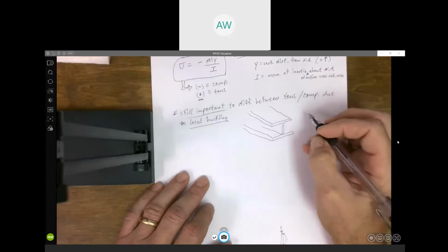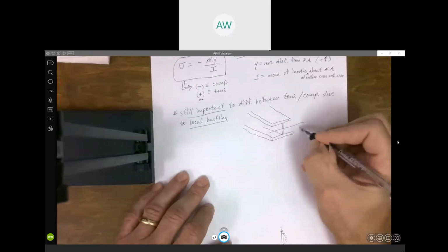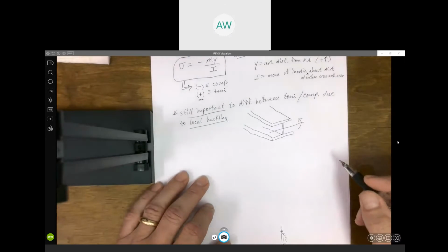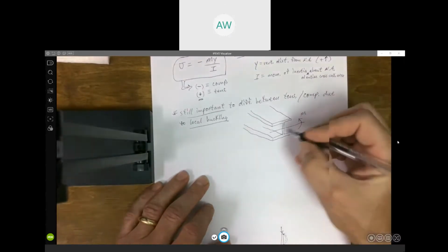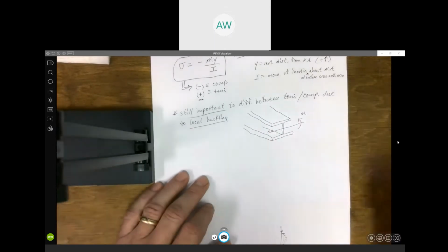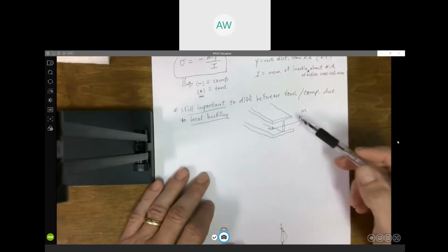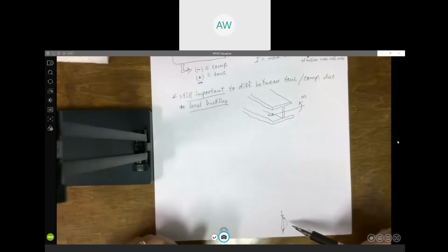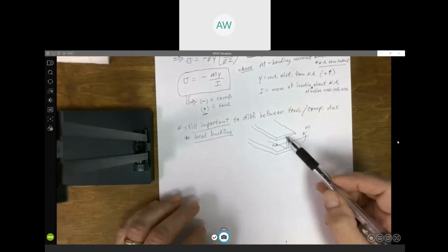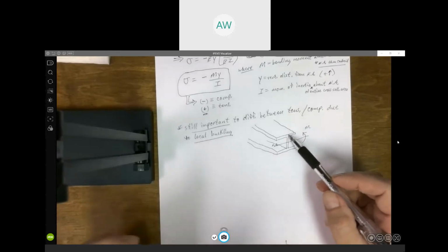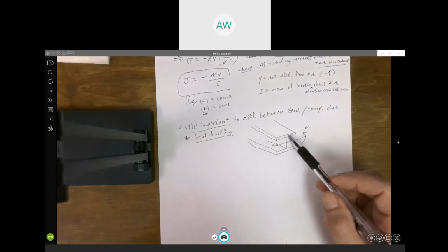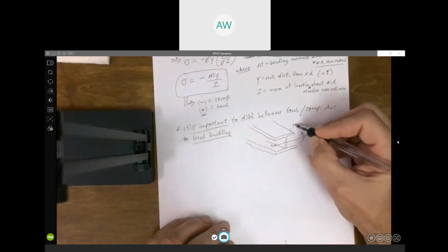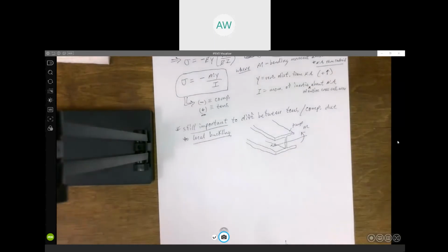All right, well, if we bend this thing, say we bend it this way, we apply some moment here. Everywhere above our neutral axis is going to be in compression. Well, that's not going to buckle like this axially loaded member. But if you have really wide, thin, we'll discuss some terminology later, these are called the flanges. So this would be the flange. What you could see is that flange will buckle.